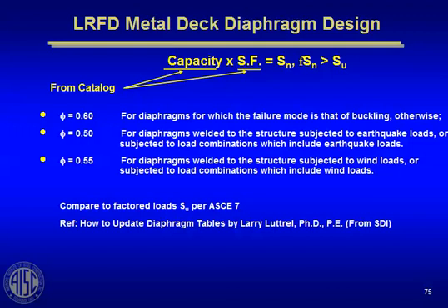Again, this is discussed at length in this diaphragm design manual by Larry Luttrell from West Virginia University. He's the one that received the commission to do the research on behalf of the Steel Deck Institute. Again, different phi factors for different conditions. Be sure to look in whatever code you're using for the appropriate phi factors for your condition.